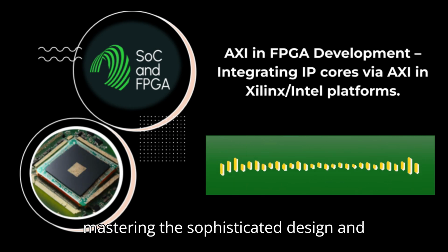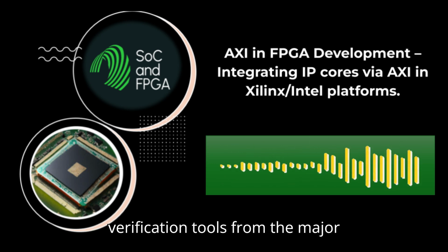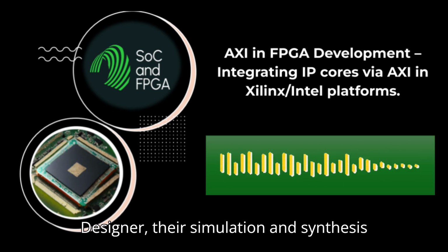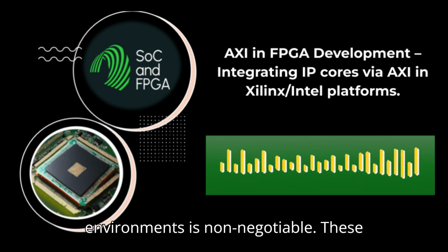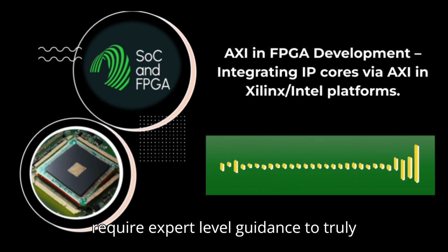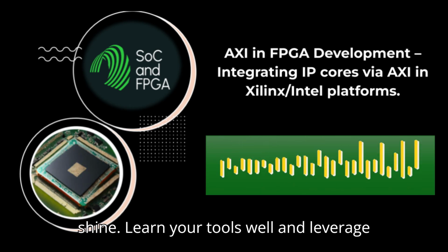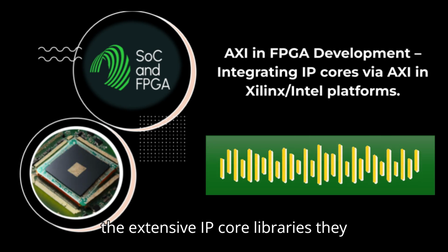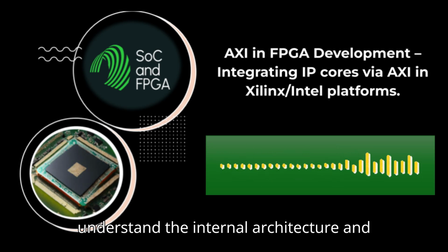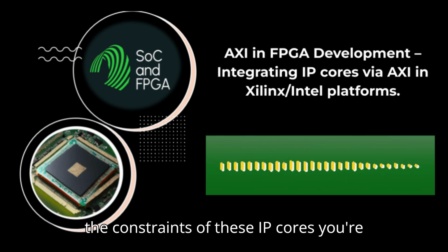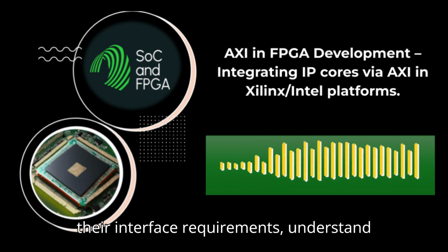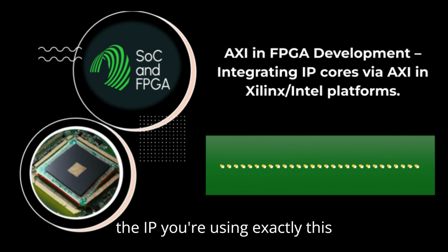Finally, on tooling, mastering the sophisticated design and verification tools from the major vendors, Vivado, Quartus, Platform Designer, their simulation and synthesis environments is non-negotiable. These tools are incredibly powerful, but they require expert-level guidance to truly shine. Learn your tools well. And leverage the extensive IP core libraries they provide. But crucially, take the time to understand the internal architecture and the constraints of these IP cores you're using. Don't just treat them as black boxes. Know their performance limits, their interface requirements. Understand the IP you're using.